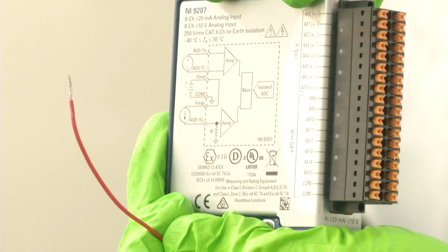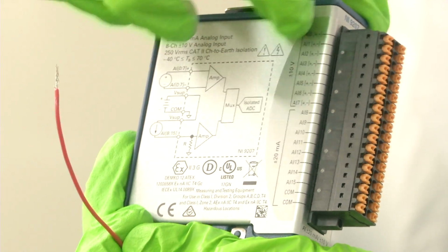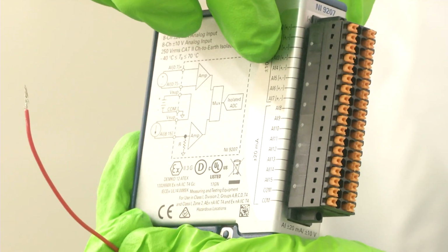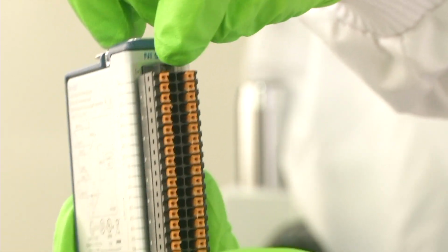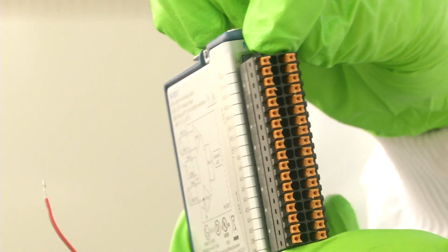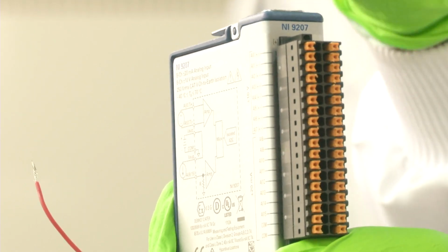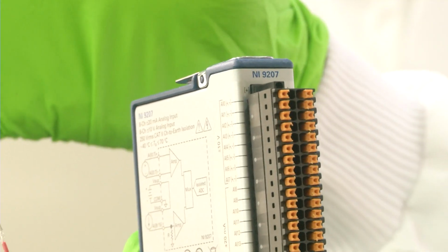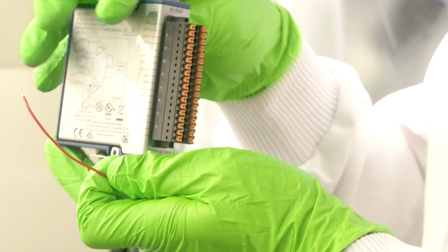So, here if you see there is a different number of channels starting from 0 to 7. So, in total it has 8 channels for analog acquisition, which can measure up to plus or minus 10 volts. So, it has both positive terminal and negative terminal. What it does is that it can measure a differential input. In some cases, when you are using a quarter bridge or a half bridge or full bridge, the voltage signal generated from the bridge is not an independent voltage, it is a differential output voltage. So, if I want to make use of a differential input, one way to do it is that we have to make use of this device.